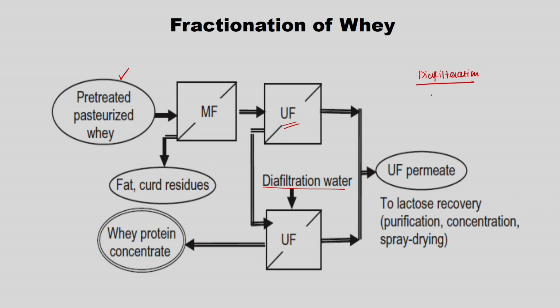I take the retentate of ultrafiltration, add some water and go for another ultrafiltration module. This is diafiltration. So, we add the diafiltration water to the retentate which comes from the first ultrafiltration module.